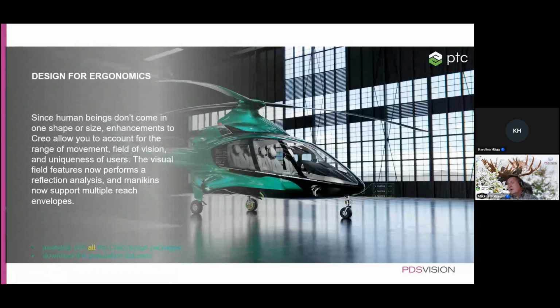So today, this design for ergonomics is included with all the Creo design license packages. All the modern license packages contain all of the following that is coming off this slide. The only thing you really have to do to make it run is to download the population datasets. We have a mannequin library in there, which you have to download, which does not come with the standard installation, in order to make all of this work with Creo 10.